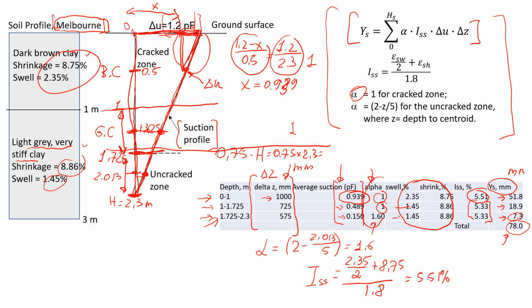You can go back to the previous slide and look at the table. You will see that it's more than 70-75 millimeters. So this is very reactive soil, and something needs to be done before you go with some construction of lightweight buildings there.